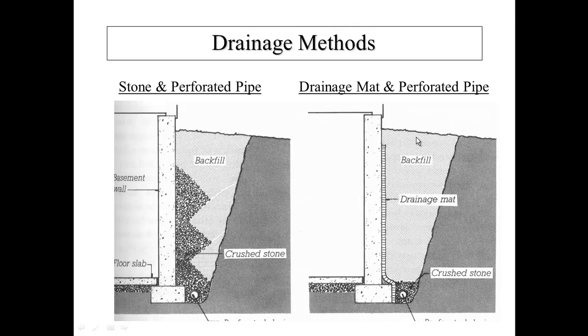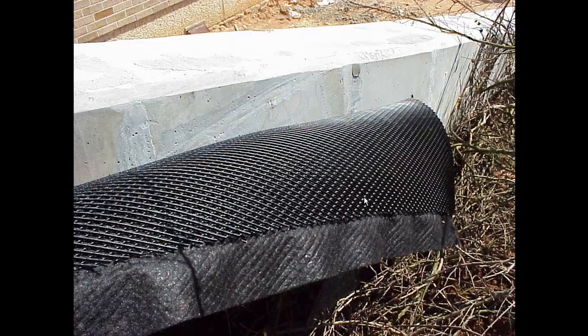If you start getting little ditches along your roof line, you want to keep those filled in with stone or something that's going to keep the water off, or even putting some type of drainage mat there that will keep the water from getting along the foundation. Here's a photograph of some drainage mat material that goes up against the foundation wall and just allows water to quickly escape from the edge of the foundation wall and get down into your drainage fabric.